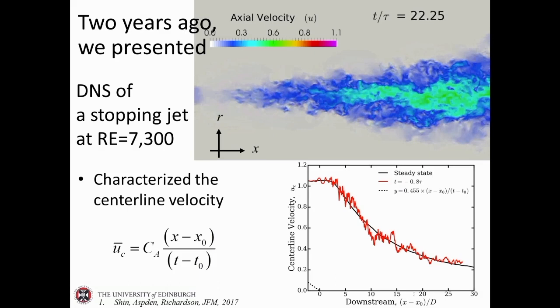So the center line velocity will increase over x, which is very strange, but you'll see how it looks like. And then inverse of time. And then if I plot, you can see the decrease of the velocity. The dashed line doesn't work at the beginning, but you can see that after a certain transient time, it starts to work, and quite interestingly, this black line is also proportional to x. Of course, it is decreasing over time, but quite interesting that it's linearly increasing with the x.